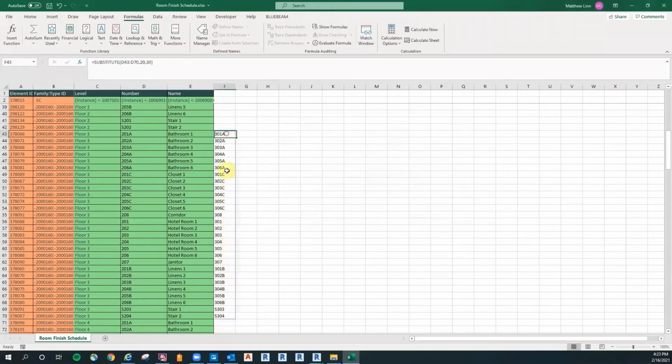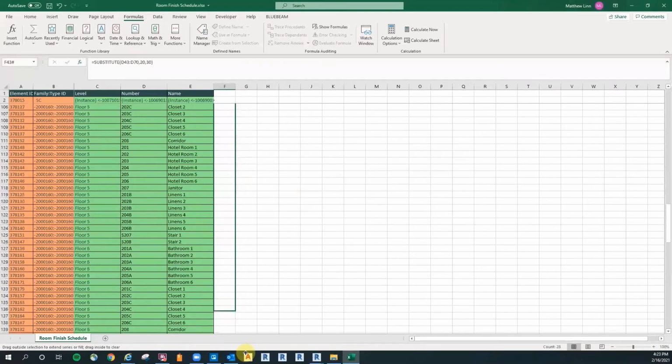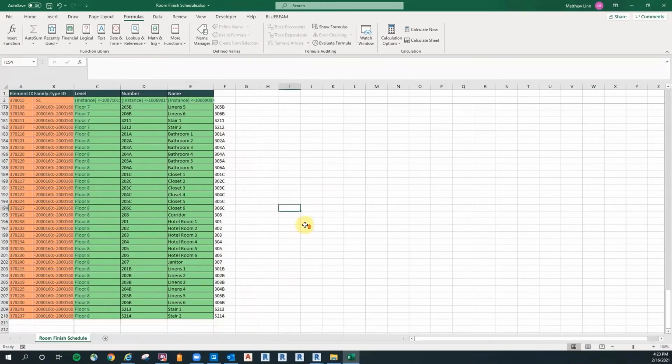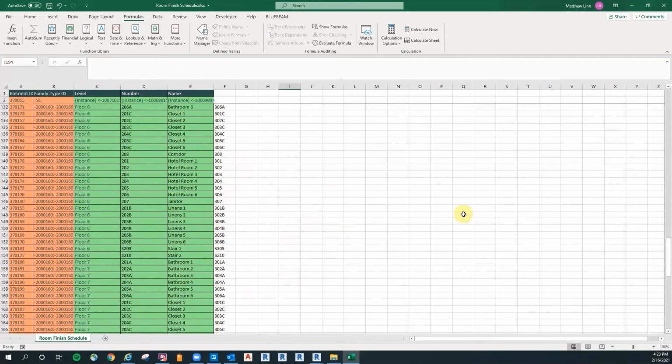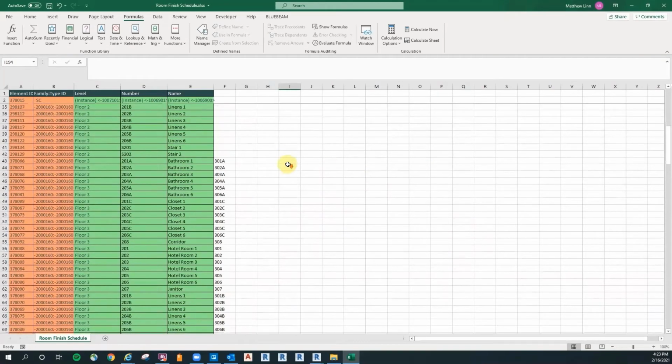Okay, what about the others? Now I can grab this entire thing. Again, you can see the top, that's defining the formula. All the cells below it are reading the autofill function from that formula placed at the top. But I'm gonna grab the whole thing and autofill the other 6 levels, or 5 or whatever. Okay, now you can see they're still taking on that 3rd level naming convention, but now the infrastructure is in place where I can just go to the top cell of each floor and swap out in the function a 3 for a 4.